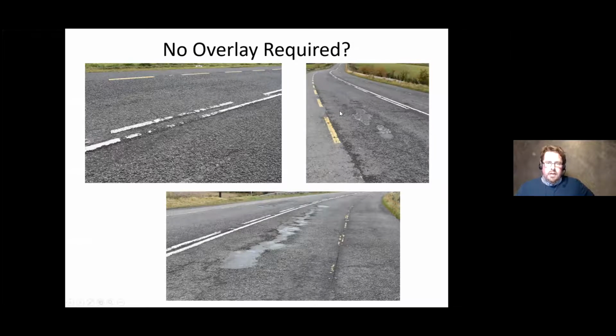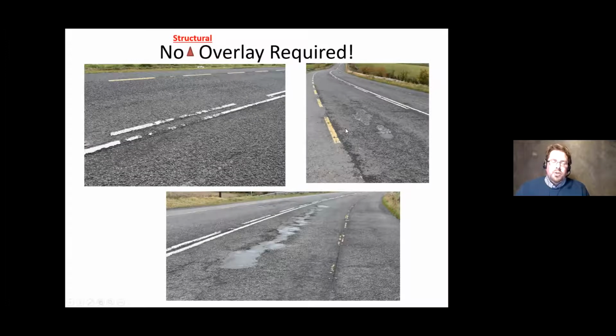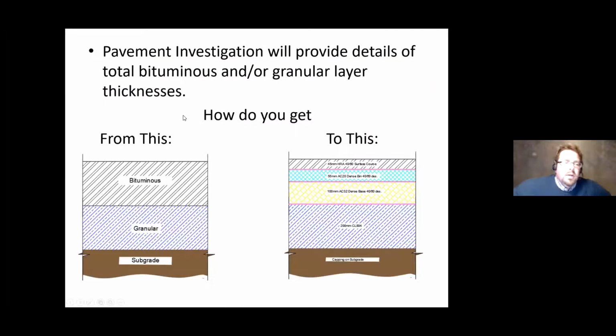This particular stretch of the N2 had, I think it was 12 MSA design life, over 20 years. So you can see that it wasn't going to last much longer, even though there was a no overlay requirement. So you have to be conscious that it's a no structural overlay requirement that you're getting back from your FWD operator. So you still need to carry out works, and you still need to carry out structural works, but the overall structural capacity is adequate. So you're effectively replacing what you have with similar depths of a better, more modern material, or just newer material.